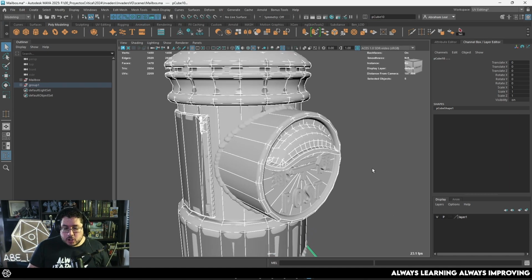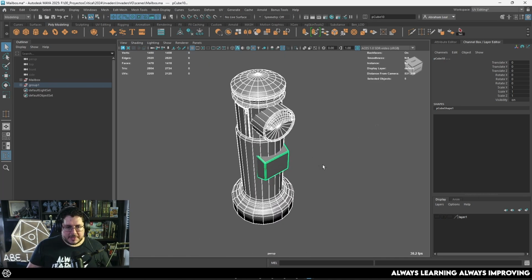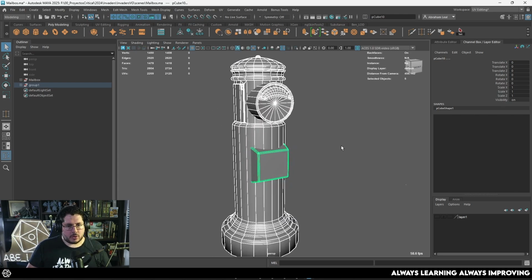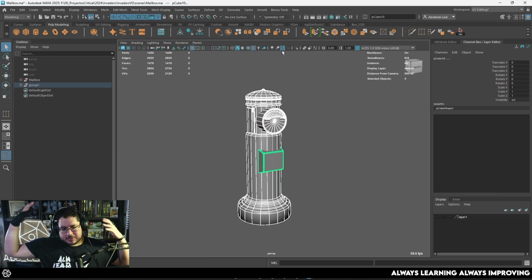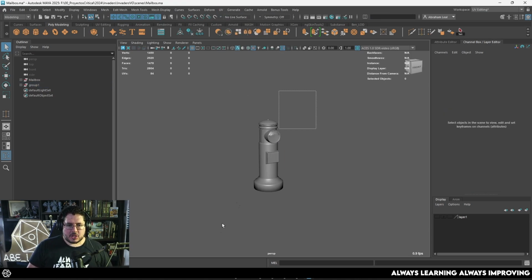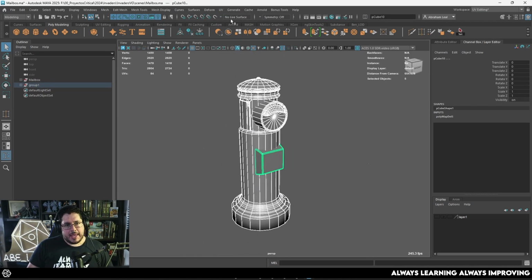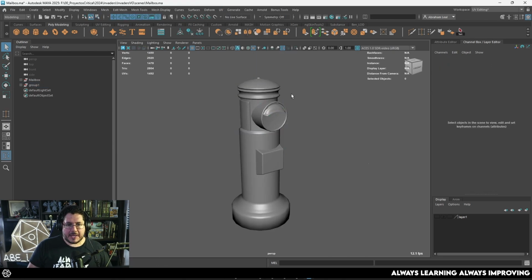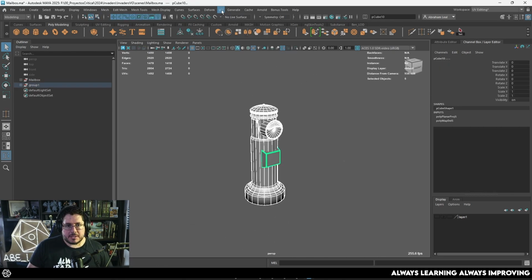So let's now jump onto the UV section of things. For UVs, I'm going to use the method that I've shown before. I've shown this everywhere here on YouTube, in the tutorials, which is the 5 steps to good UVs, right? So I'm going to go here to UV, and I'm going to delete UVs first of all, to make sure that we don't have any UVs on this object. And then I'm going to say UV, and we're going to do a very basic camera-based mapping. This is just so that we have a UV set, right?